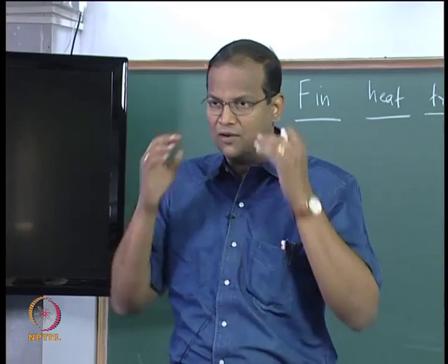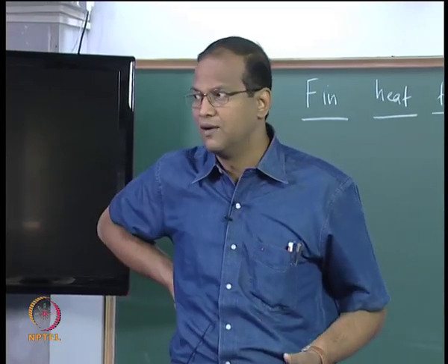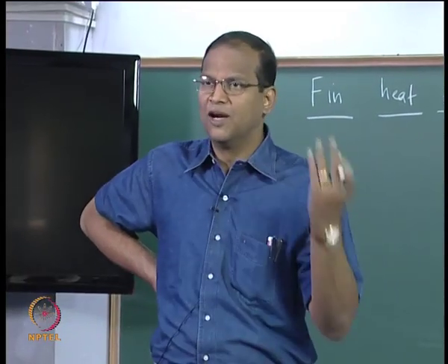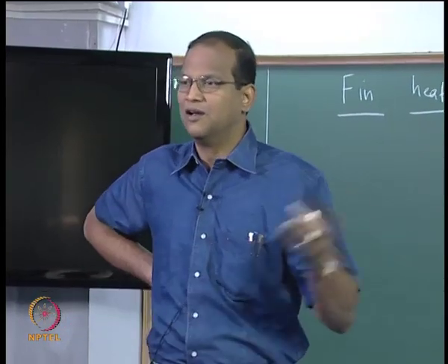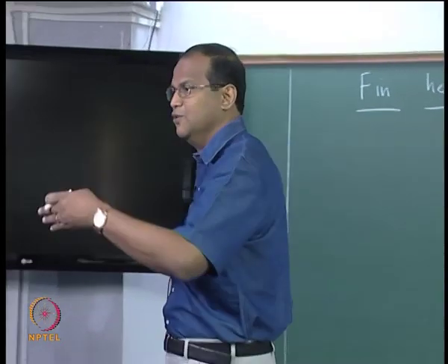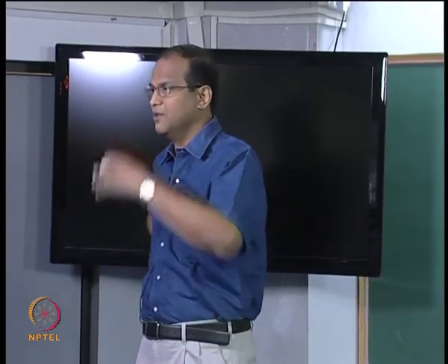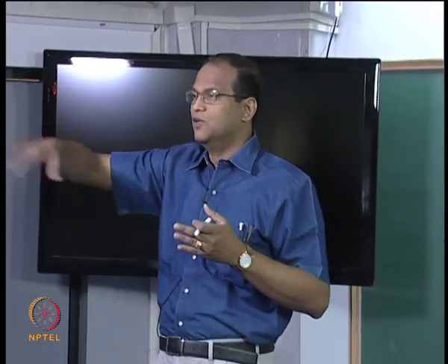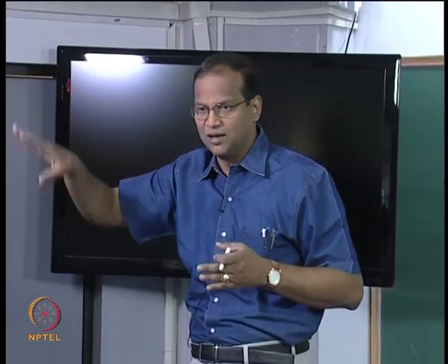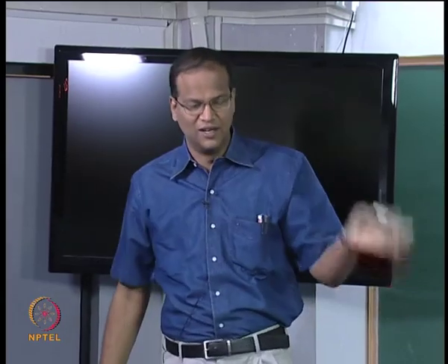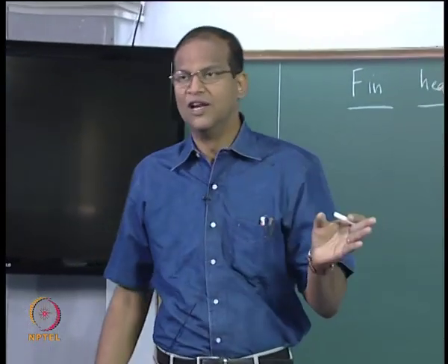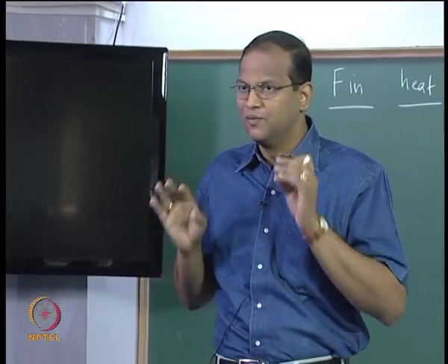So, you will do scale down experiments, or you do experiments on water, and then from water you know the Prandtl number of water, you know the thermal conductivity of water, you know the Prandtl number of sodium, and using your fundamentals of Reynolds number, Prandtl number, Peclet number, Nusselt number, you see whether you can map. So, if this is the heat transfer rate I am getting with water for the scale down reactor, what will be the heat transfer I will get for the full reactor with sodium, something like that you have to do, right.